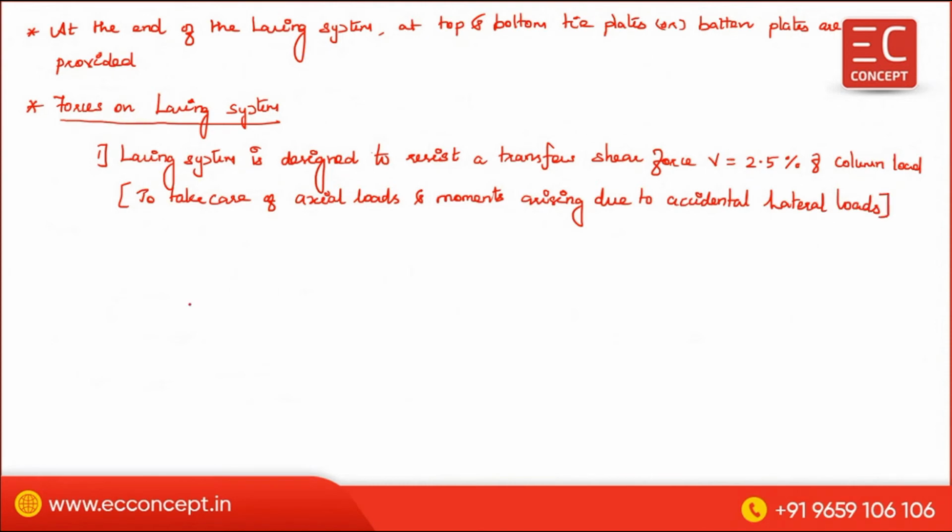Okay, now second point is force shared by, that is force on lacing bar, which is equal to V divided by N sin theta.